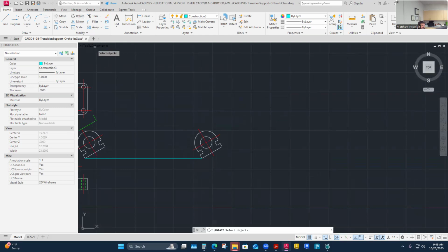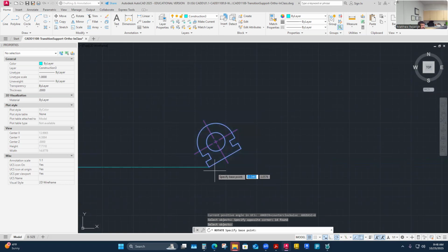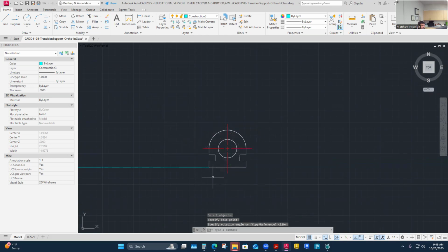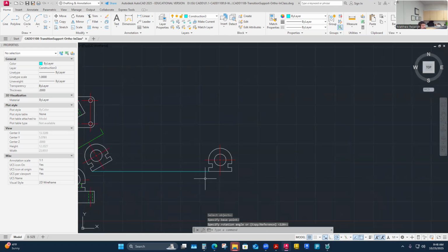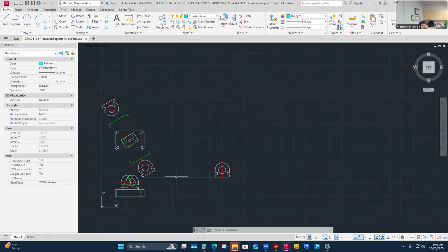So maybe I'll rotate this, choose my rotate command. If I want to keep it on that plane that I established with this line, maybe I'm going to rotate it by this, right? Then I'm going to rotate it down. That looks better to me, like slap it down to 0. So that's a 30-degree rotation down is what I've done there. And that makes sense. It was on a 30-degree twist. So I just rotated that by the base, so it stayed on my base and in projection plane a little bit. So it's just me keeping that relationship.